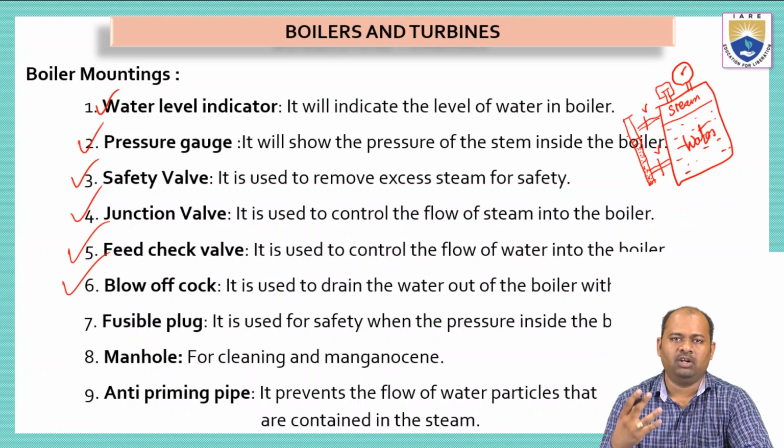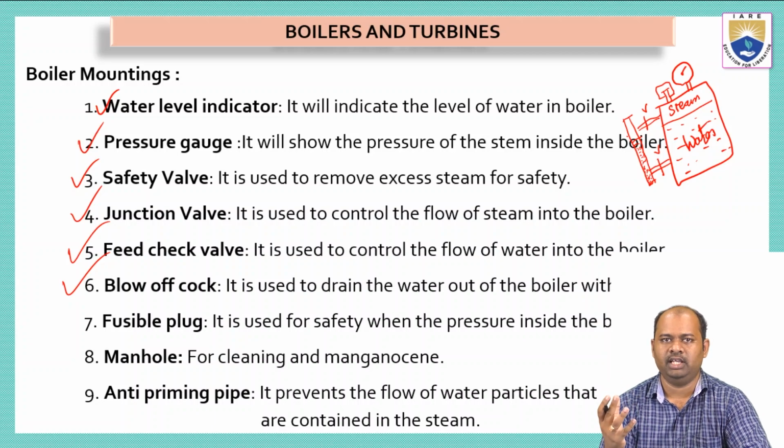We know the water will contain a large amount of carbonates and bicarbonates. Due to heating, these salts will be deposited on the inner surface of the boiler tank. Now, we have to clean this somehow. After some working days, we have to clean the boiler inside so that we can use the boiler more effectively.